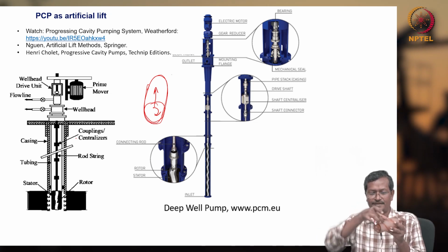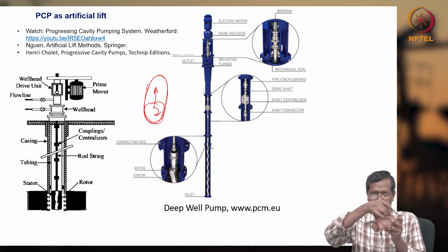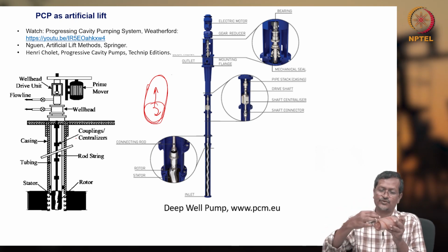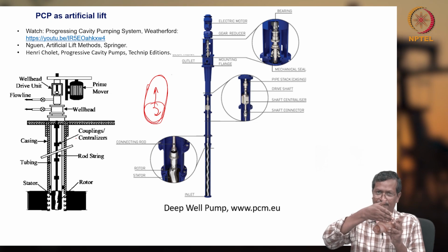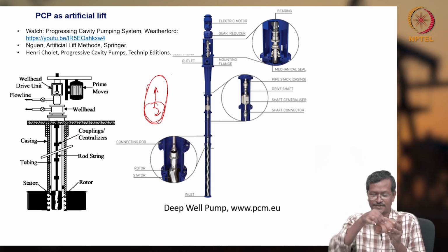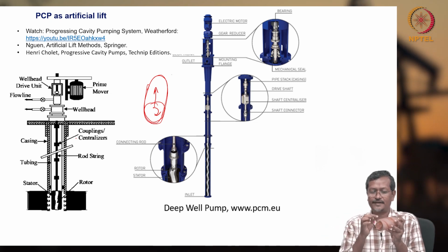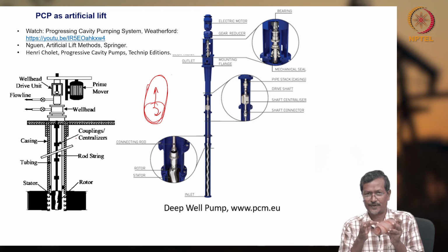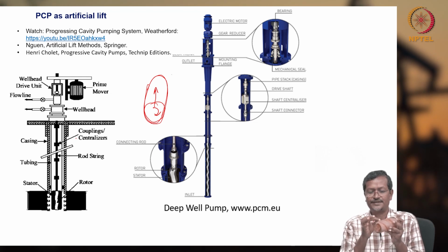Okay. So, small cavity is here, another cavity is here, one cavity here, another cavity here. So, one cavity means two seal lines will be there. You are blocking this and creating a small cavity, and if the seal line is not sealing properly between rotor and stator, then there will be leakage.